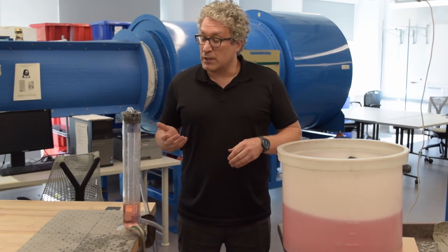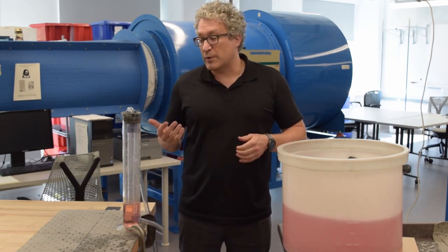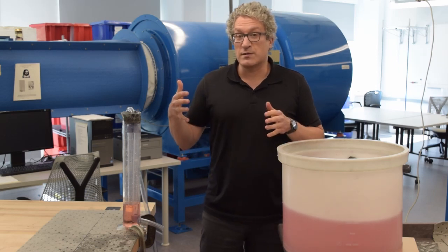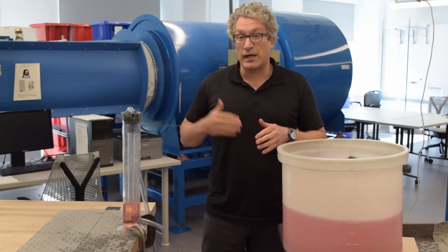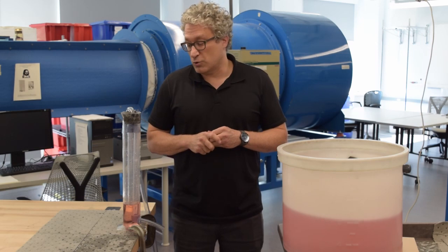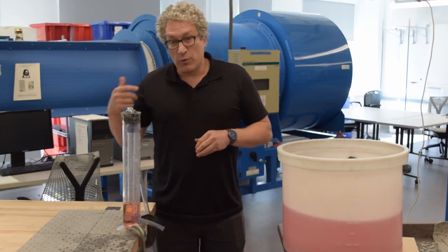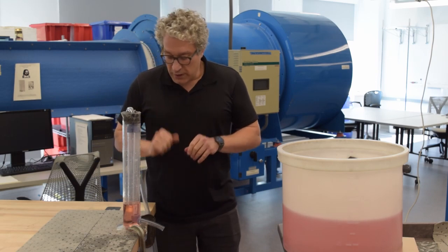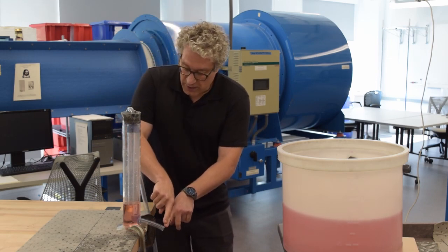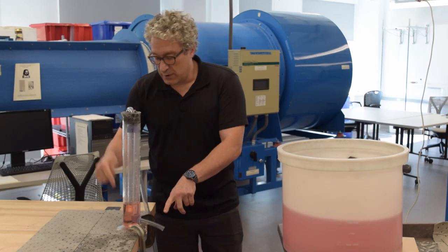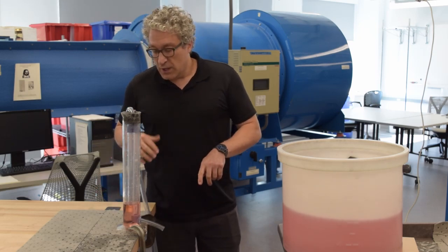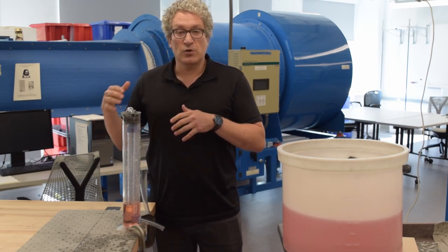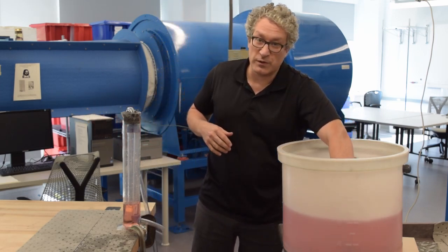And this is used commonly in urinals and men's restrooms. This is commonly used in a variety of different hydroponic and aquaponic cultures to create systems that naturally fill and empty without having to use any active control system. And you can do that with what's called a bell siphon, and that's shown here. This is just a graduated cylinder, but inside there's a tube that starts here at the exit, loops up, and then loops down. And the reason why this is a convenient configuration is that this allows a system to oscillate back and forth between two different states.